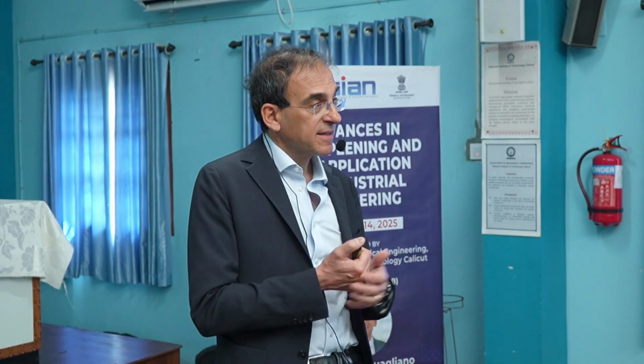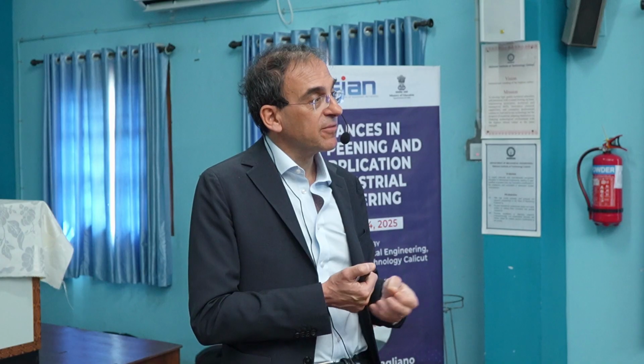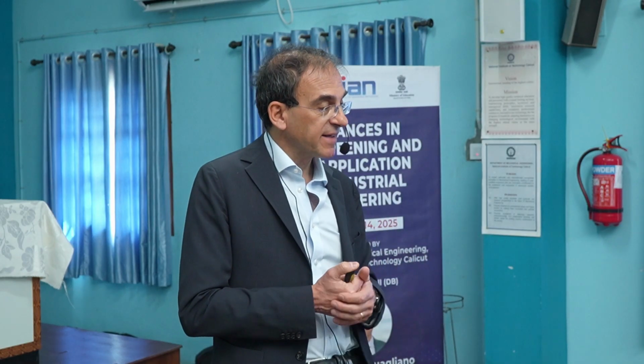If we know the applied stress, we can have an idea of the desired residual stress we need, and then we can choose the right intensity, shot time, and finally the coverage. This is the scheme of the design of the air peening treatment.